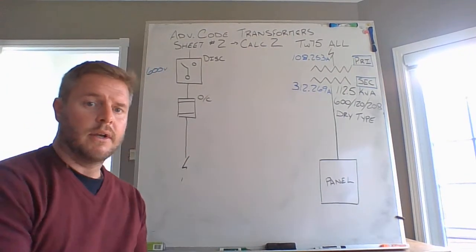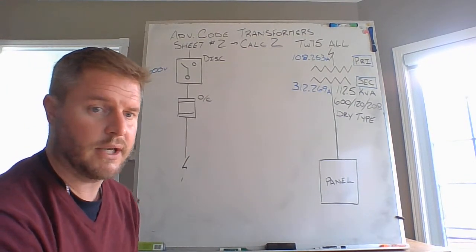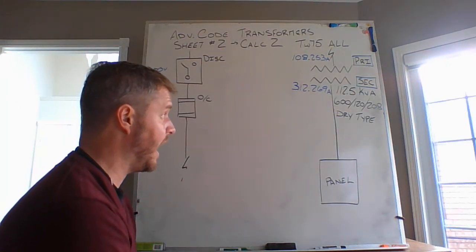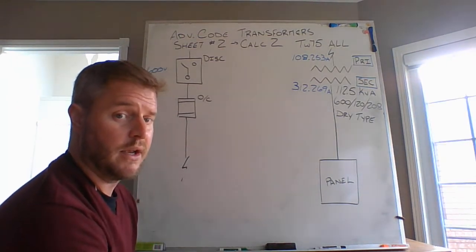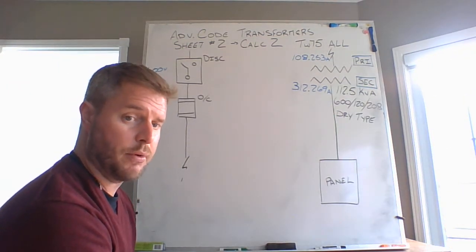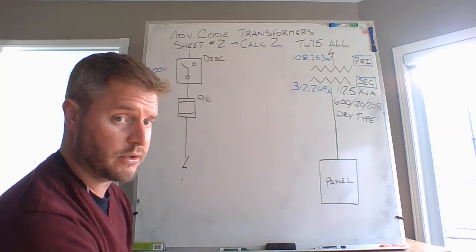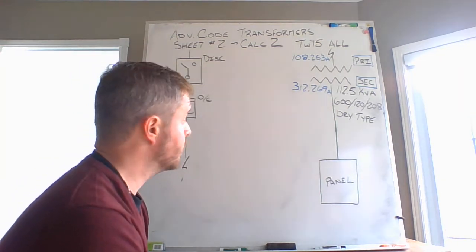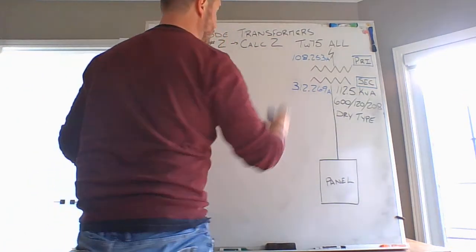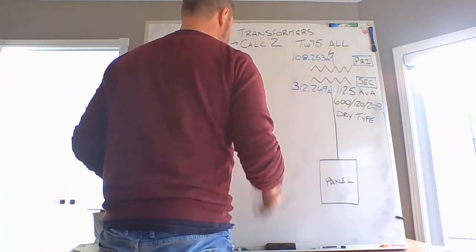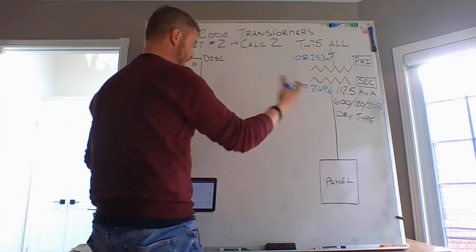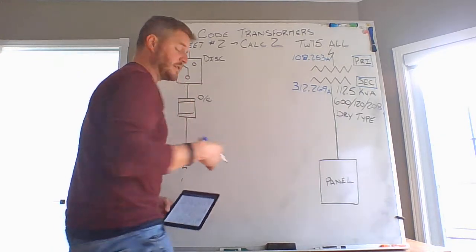Okay, secondary side, transformer calculations. We're looking at 312.268 amps on that 112.5 kVA transformer with a secondary output voltage connected in a Y configuration of 120/208. So my full load current rating on my secondary is 312.269 amps. To figure out my conductor's ampacity on this side, the secondary side of my transformer, it's the same calculation as the primary side.